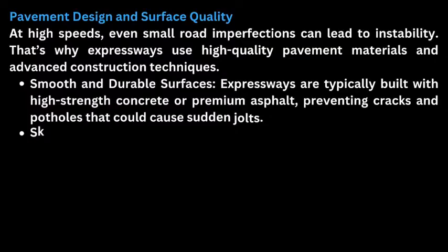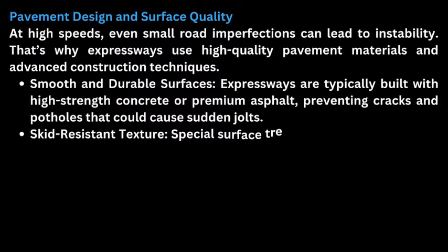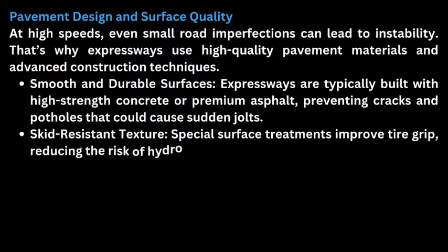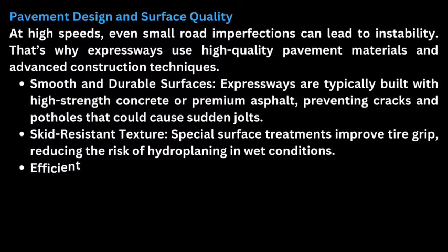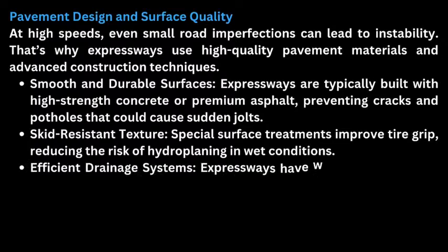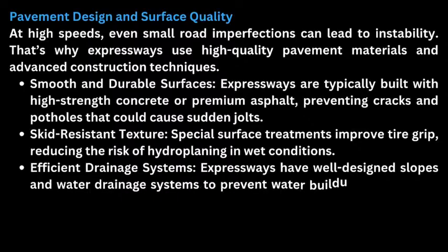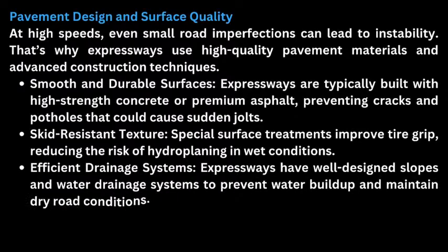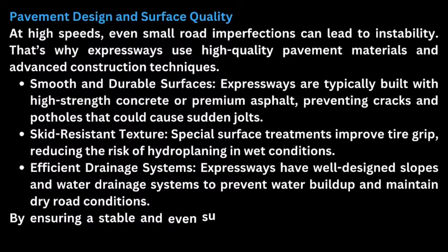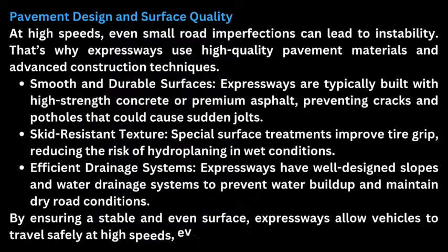Skid-resistant texture. Special surface treatments improve tire grip, reducing the risk of hydroplaning in wet conditions. Efficient drainage systems. Expressways have well-designed slopes and water drainage systems to prevent water buildup and maintain dry road conditions. By ensuring a stable and even surface, expressways allow vehicles to travel safely at high speeds, even in bad weather.